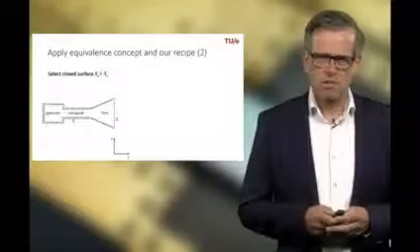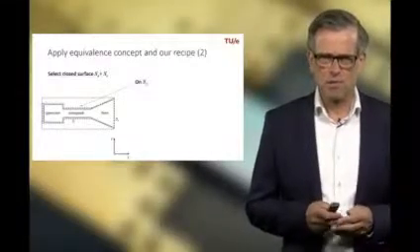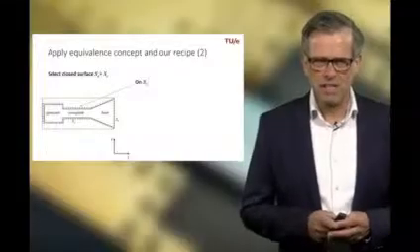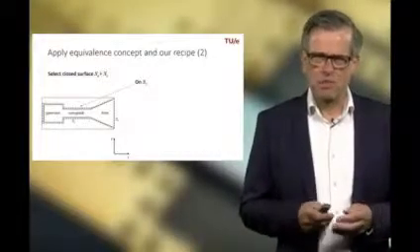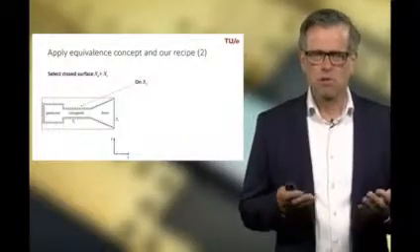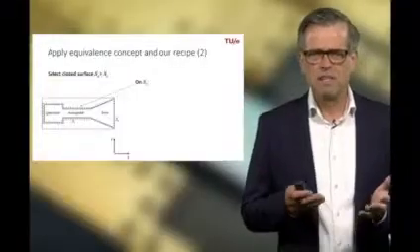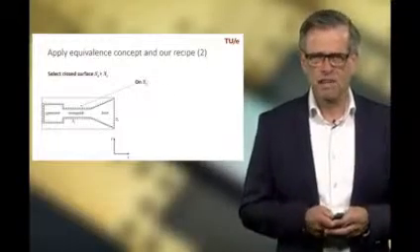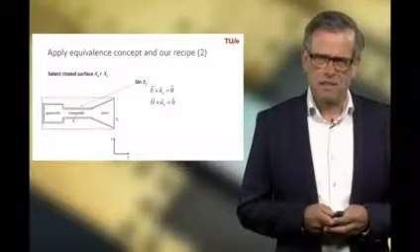So the coordinate system is shown here again, and on SC, so that's the first surface, excluding the radiating aperture, we will assume that it is a perfect electric conductor, which means that the tangential electric field will be zero, and we will also assume that currents that might flow on this surface can be neglected. So also the tangential H field is zero, as indicated here.